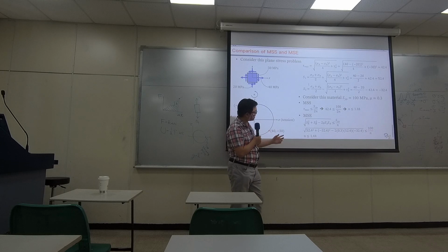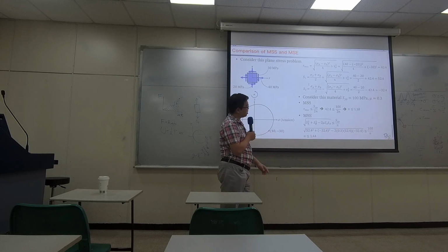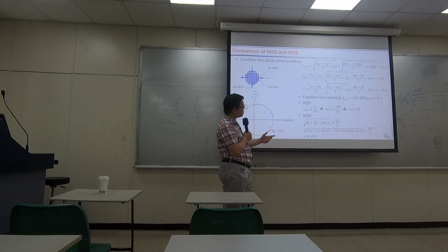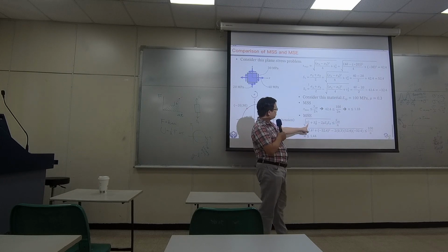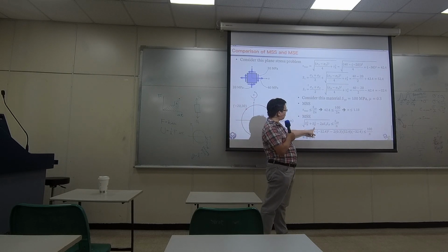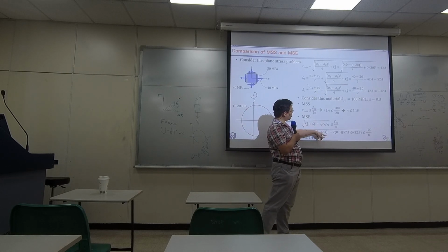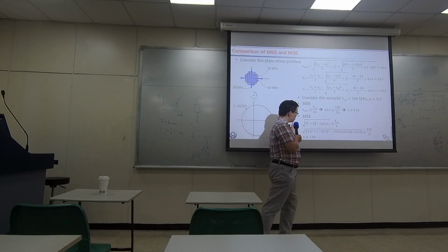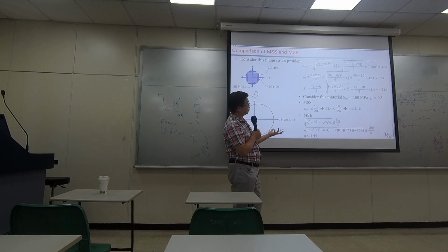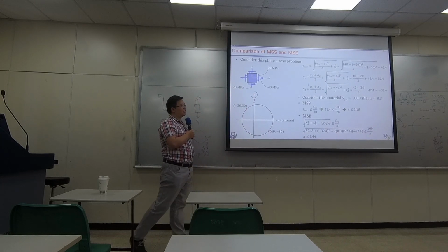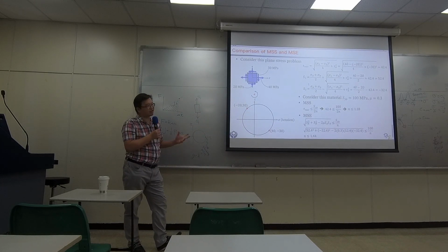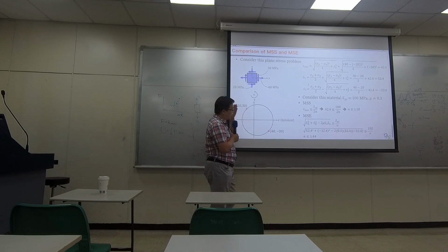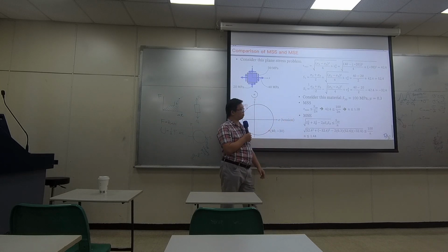So let's try it. Using the equation that we derived earlier, plugging in all the numbers, first principal stress, second one, Poisson ratio here, and also the yield strain, and truly compute what's the maximum safety level I can reach under the concept of the strain energy model.